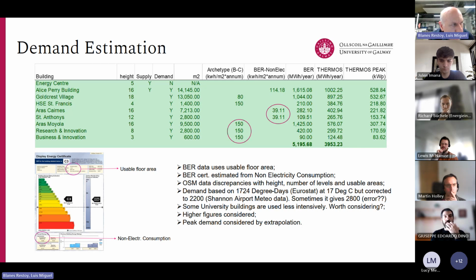We did that for the geothermal project, and it saved us a lot of headaches. Install heat meters or have meter data or gas meters and submeter as much as possible. If possible, even a small investment saves you a lot of uncertainty. And uncertainty is a driving force when you talk about investments. So we currently have no data available on gas meters.